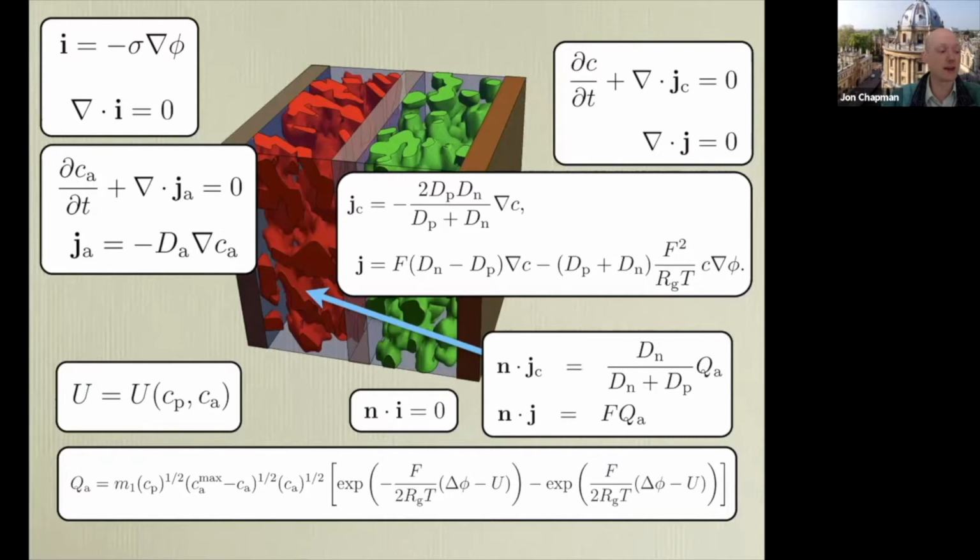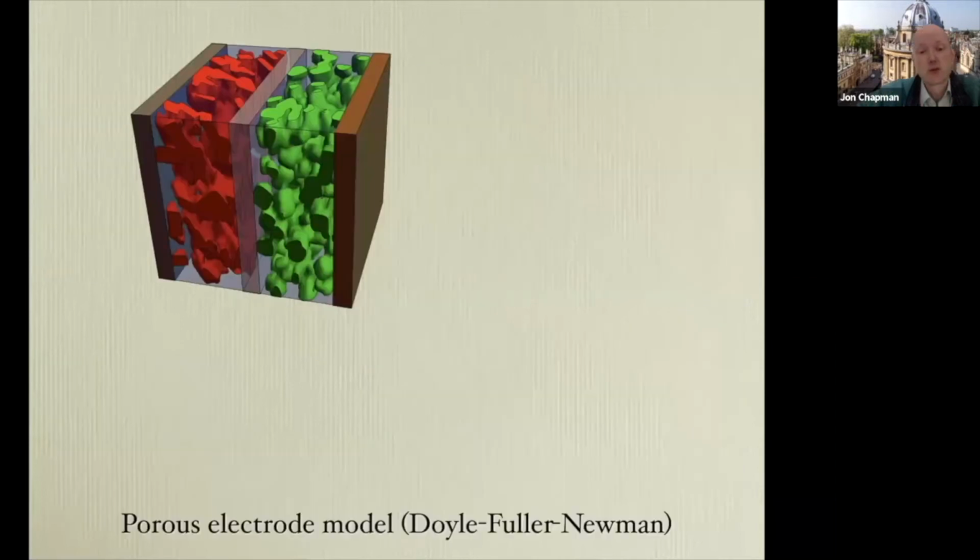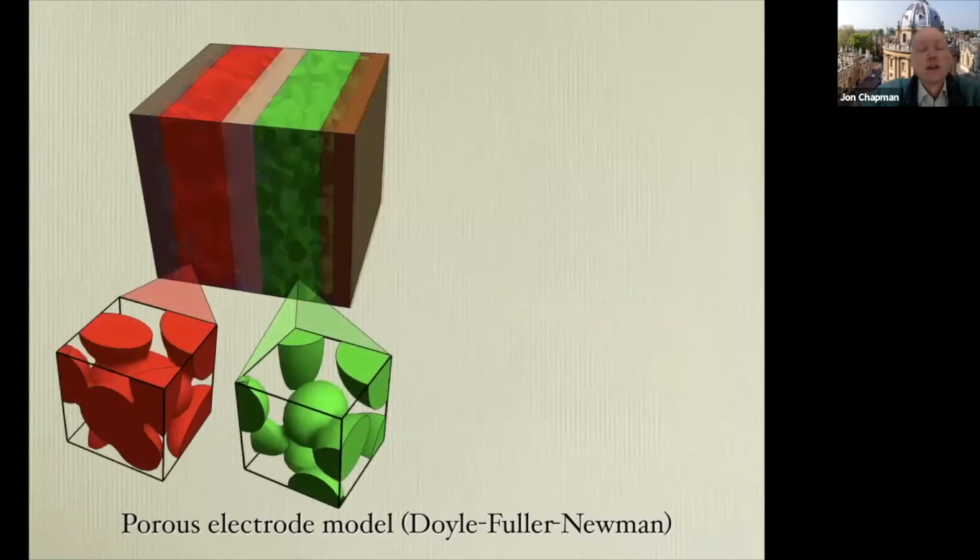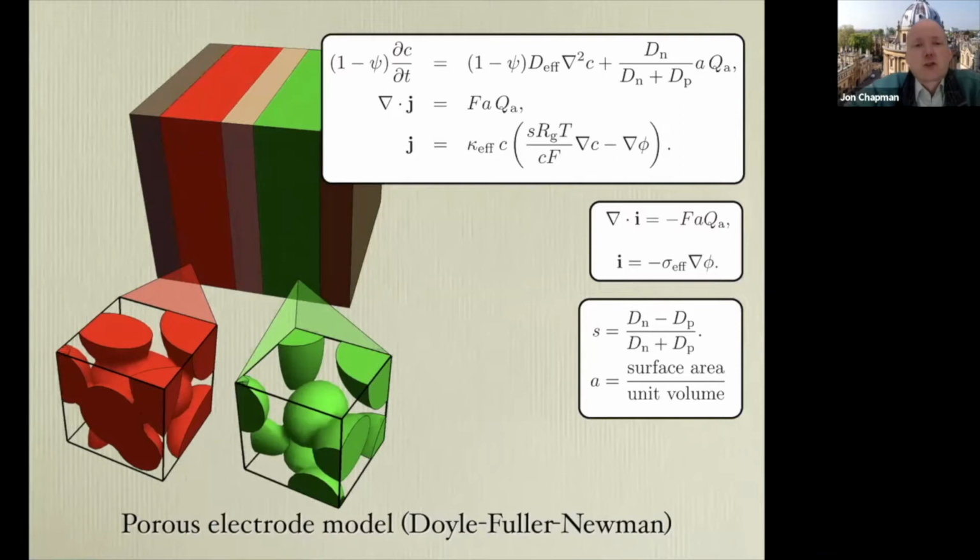And the first step in that reduction is to go to a porous electrode theory by doing a homogenization. So you can do this by systematically, mathematically homogenizing such an equation. And what you end up with is this sort of system where I now have a set of equations to solve in the porous electrode, and therefore I solve both for the concentration in the electrolyte and for the electronic and the ionic current in the same region of space.